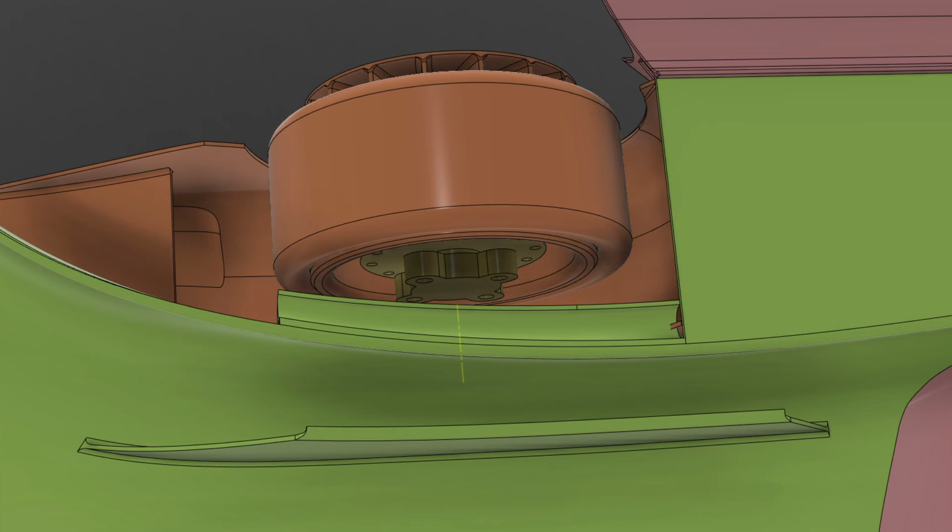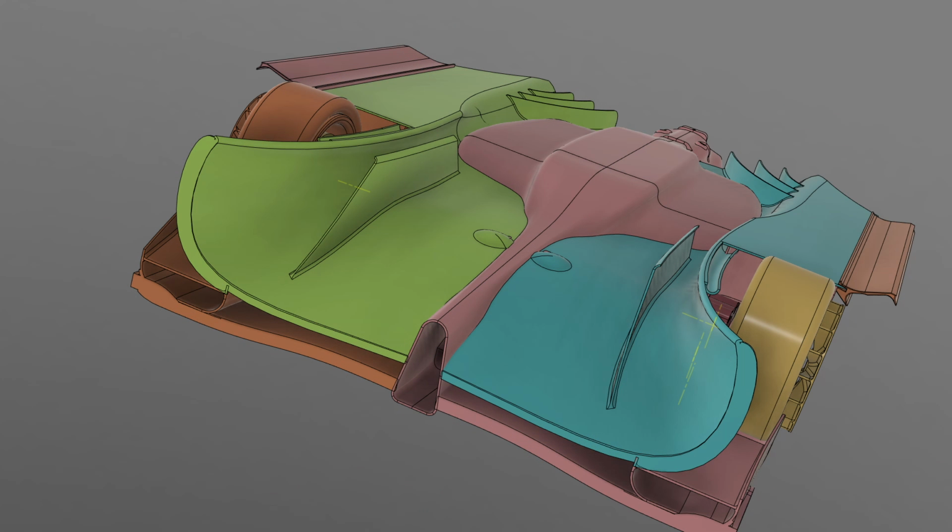Another feature of the underfloor is we have some vortex generating tubes right here next to the rear tires to help minimize the wheel wake or the tire squirt being spilled into the diffuser. Additionally, we have two strakes which help to compartmentalize the losses from the rear wheel wake. If you want to check more about this, Kyle.Engineers has a great video on diffuser strakes and their functions.